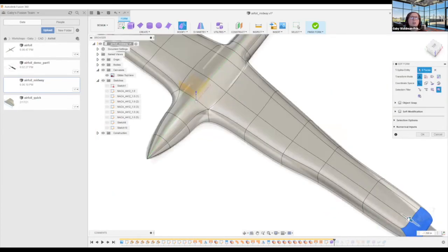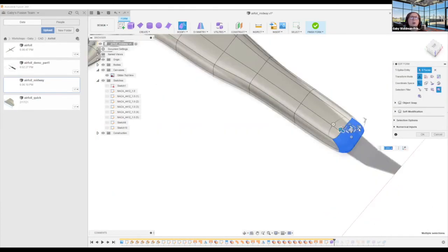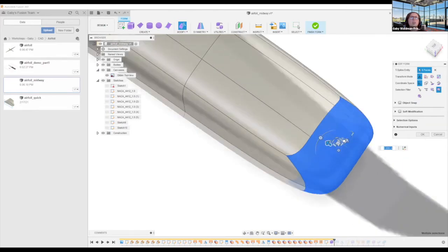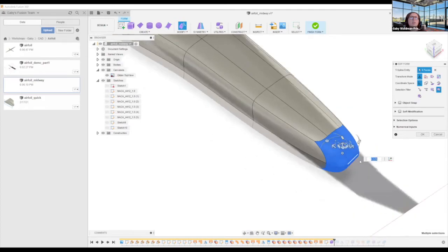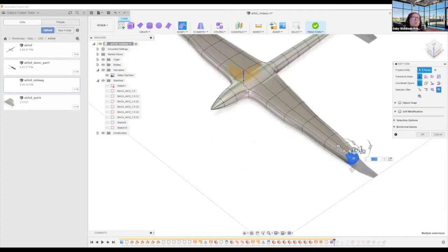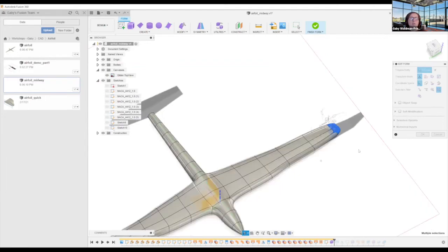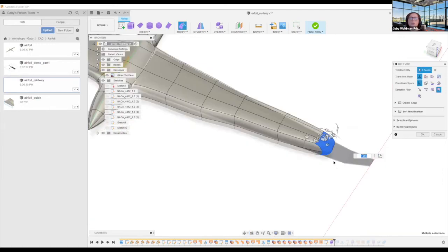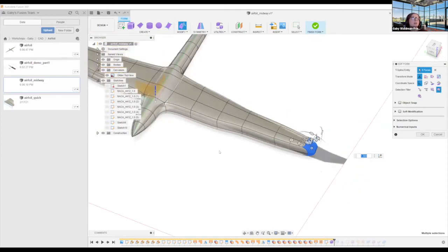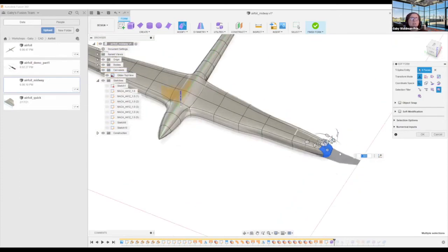Yeah, so you can see how with some concerted effort getting the shape right, you can get a pretty good shape for what you want to do. And in some ways it's a lot less work than a loft, right? With both surfaces and solids, you have to do the loft. It's parametric, meaning it captures all your history. With form, it doesn't capture your history, but you can make stuff really fast. It's taking me way shorter to make this.